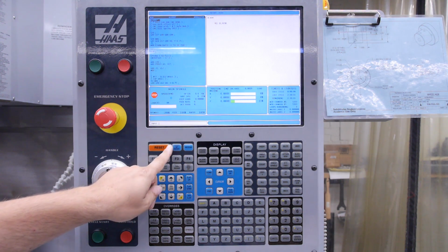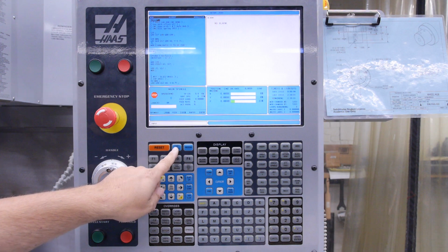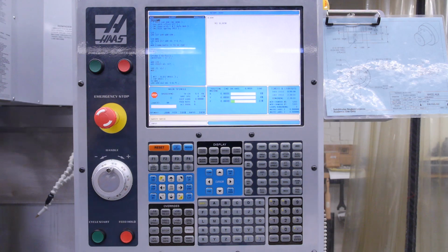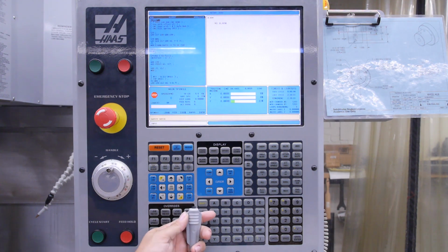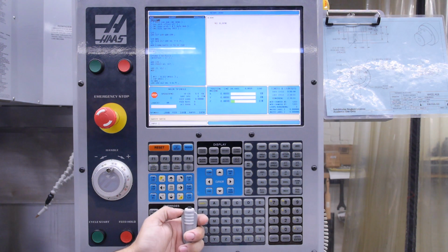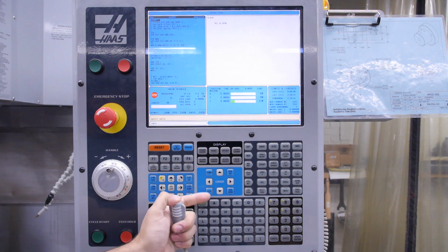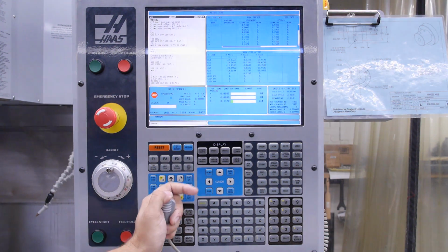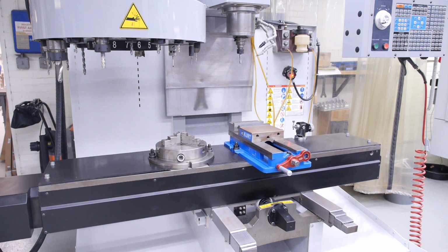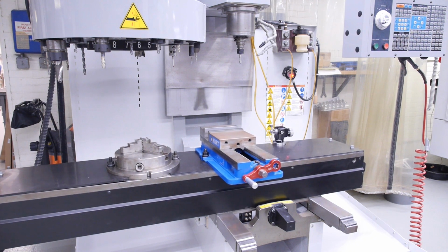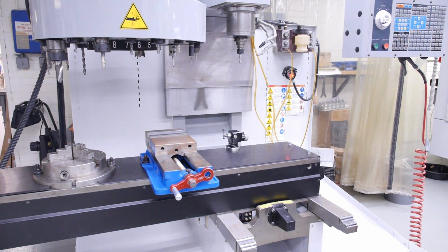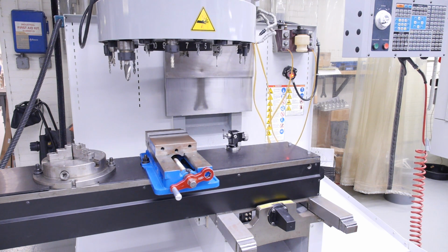This button is located to the right of the orange reset button. If we press it, we notice an alarm message is generated which says safety switch. In this case, we have to retrieve the dead man safety switch off the back side of the machine, press the button and hold it, and then press the power up restart button on the CNC. At this point, as noted on the outlines, the machine will start moving, so you need to direct everyone to stand back. The axes will home, and the tool changer will change automatically to tool number 1.